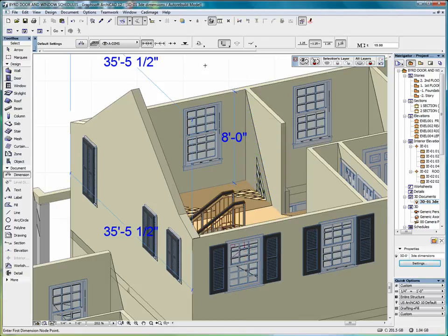When dimensioning in this view, we have this button up here that gives us different geometry methods. We can select the horizontal, vertical, or any plane. So with any plane we can bring this out. We'll see our little compass there. We can bring it this way against the wall. We can bring it to the right. We can also bring it out in this direction. So we've got a lot of flexibility with our 3D dimensioning tool, which adds additional functionality and enhances our ability to create understandable documentation.